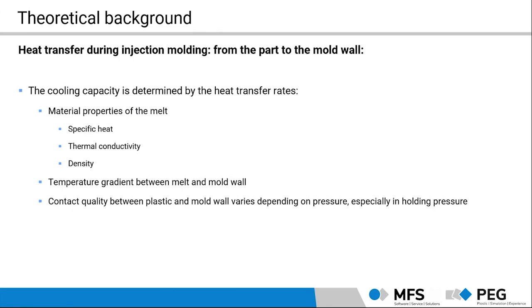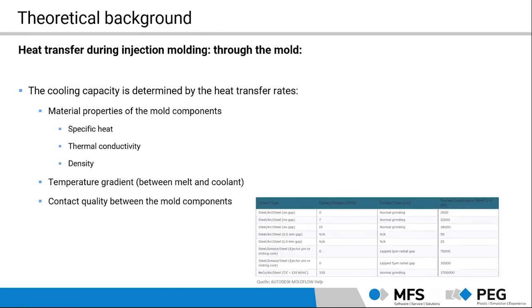Also the heat transfer through the mold itself is determined by the material properties of our mold components, and especially if you have different mold inserts, different mold plates. So the contact between all those different components is very important for the heat transfer itself.